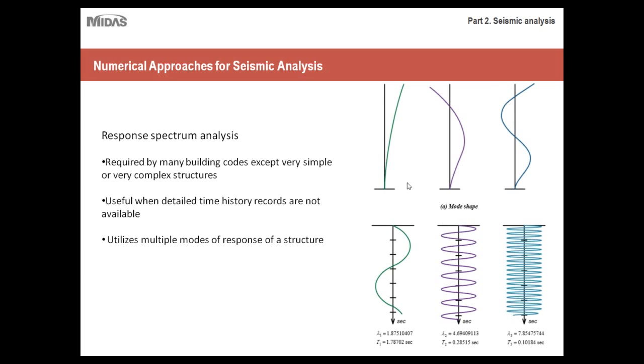So the purpose of these modes is to take each situation into account. As I said before, because seismic loading is cyclic, the forces acting on your structure will behave very differently. It'll vary from second to second. So what you'll do is take three critical modes and three critical conditions upon which the loads are acting upon your structure, and you'll perform the calculations for each one. As you can imagine, the displacement for this one would be completely opposite from this one. But both of these conditions are very realistic and very probable in the event of an earthquake.